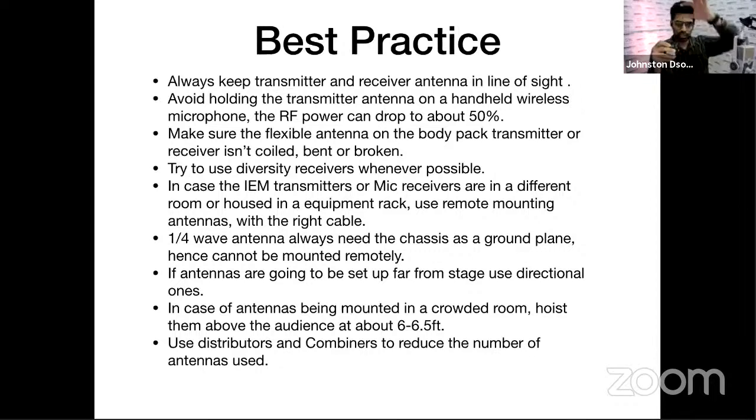Okay, make sure the flexible antennas of your devices are not bent, not curled up, not broken, because if that happens, again you'll have bad quality RF transmitted or received. Whenever possible, try to use diversity receivers, because a diversity receiver is going to increase the chance of you getting a better signal.